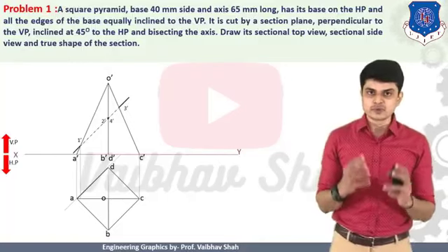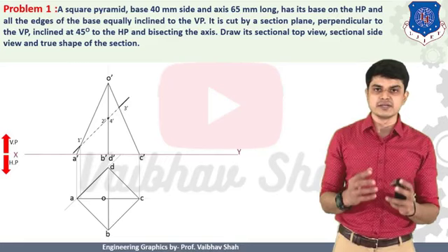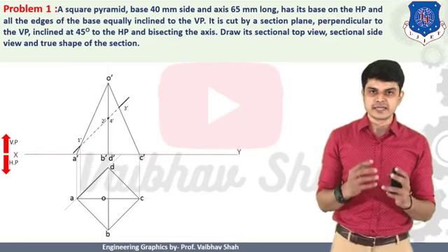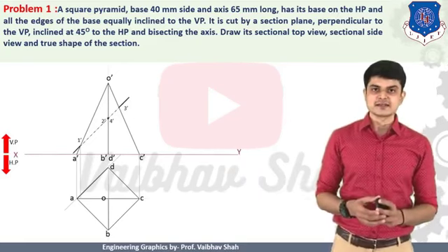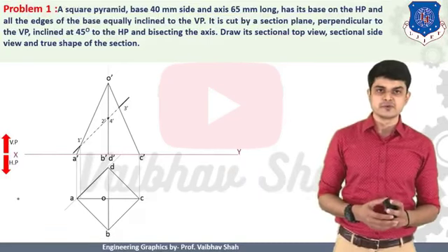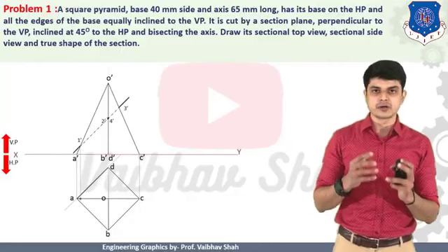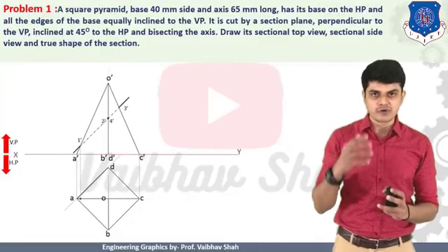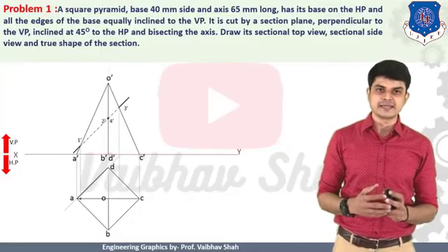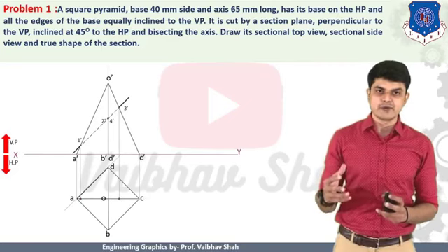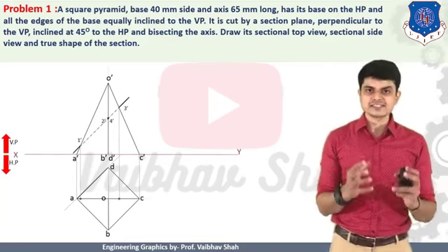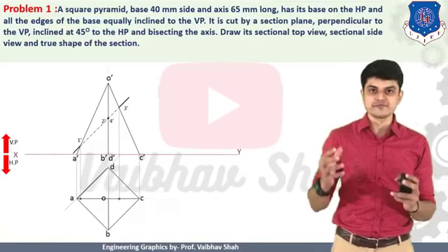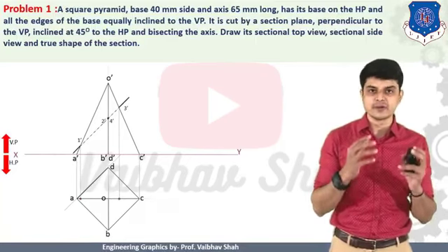So let us start transferring the points. Now let us draw the vertical line from the 1 dash point. So we will be cutting the OA line somewhere on this top view. After getting this cutting, we should mark this point. This would be your point number 1 on the OA line. Then we should draw the vertical line from the C dash point like this, and mark that point somewhere on the OC horizontal line.